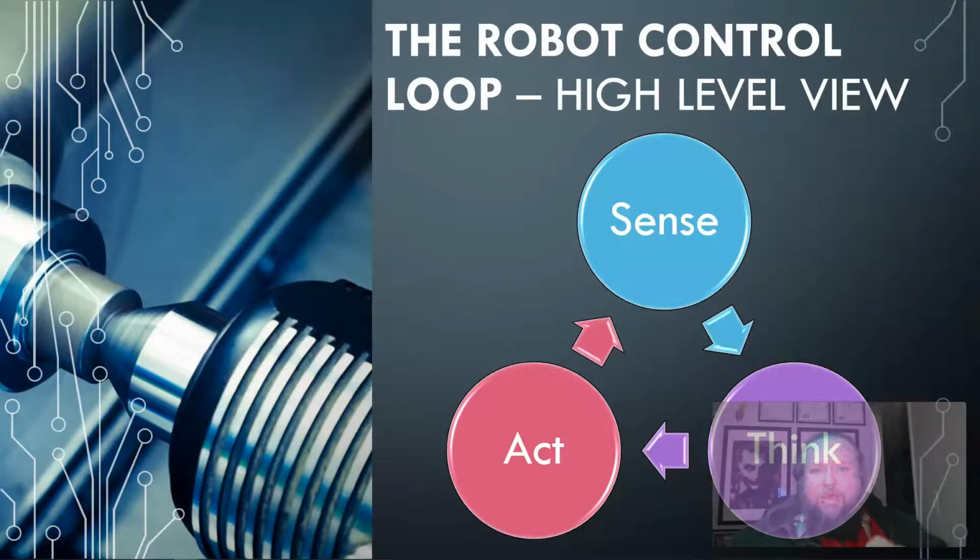So think about what's happening while the software is running versus the actual robot in a physical environment. Say it's a robotic vehicle moving forwards and you have a program that's running really slow, not taking any more sensor input and not doing any actions. If it's too long in between, it may crash into something because it hasn't read the sensors to update and think. So you have to worry about how fast the controllers we have are, how efficiently the programs can run, and how long I'm spending on a task in computer processing terms, doing some execution of actions or thinking, before moving on to the next step.